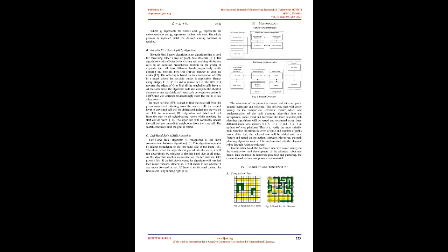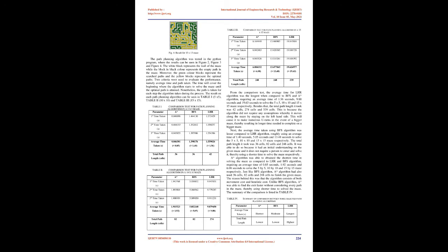9. The equation for movement cost can be seen, where g(n) is the movement cost for both the adjacent node and current node, (x, y) is the row and column coordinate for the adjacent node, while (x_n, y_n) is the row and column coordinate for the current node. The lower movement cost on the adjacent node will be prioritized. 9. The equation for heuristic cost can be seen, where h(n) represents the calculated heuristic cost, and (x_e, y_e) represents the row and column coordinate of the desired ending location, while (x_n, y_n) represents the row and column coordinate of the adjacent node.